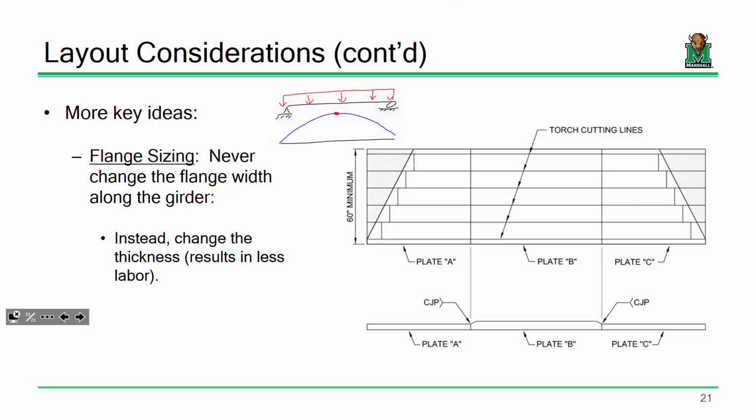Which is why if you look at girders and longer span bridges, what you find is this. Here's your flange. There's your flange. And then somewhere in the middle, that flange gets larger. Make sense? We have a flange transition. There's a point when you're going down and then the flange suddenly gets thicker, right? You don't need that massive flange right here where there's hardly any bending stress at all. You need it out at midspan, okay? So if you look at your flanges from abutment to abutment, you might use a really thinner piece and then it gets really thicker, okay?